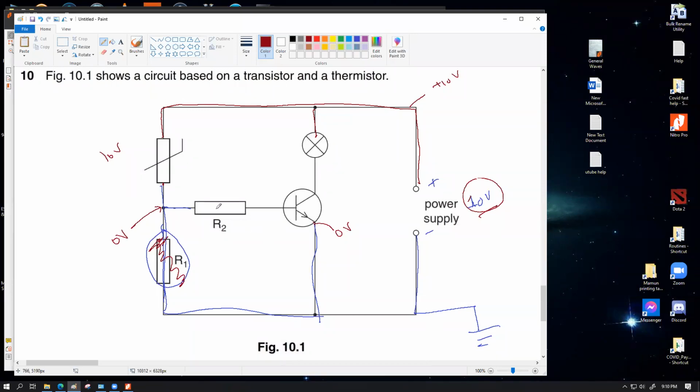So if you have both the sides of the base current to be 0 volt, would you ever have any current in this branch? No. Sir, there must always be a little current in the base for current to go from collector to emitter. Exactly. A very small amount of current will allow a large amount of current through the collector emitter branch, but you need to have some current in the base for that to be opened. Zero base current will allow you zero current to the other branch. Even a small amount of current in the base will open up the collector emitter branch by a lot, but you need to have some current allowed.